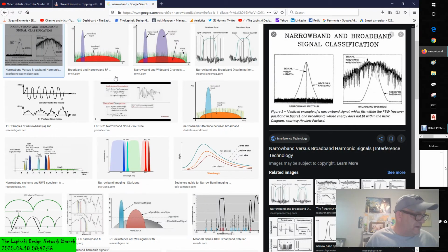Spandrel and shadowbox, often in glazing applications, the spacing of horizontal members will consist of a pattern including a narrow band or spandrel to mask the floor and ceiling sandwich. REVIT software does not currently have the ability to define two spacing values, but you can create the spandrel or shadow box in a single panel family. In the example shown here, the spandrel height is a type property of the custom panel family. Standard mullions are applied to the wall.